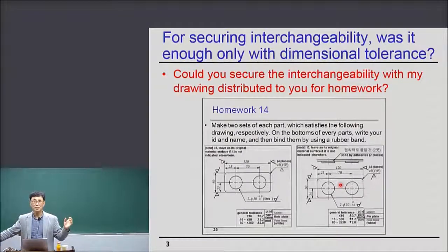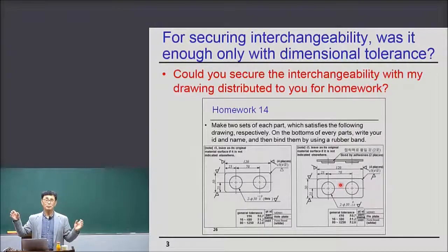And the MMC hole plate, what is it? Material maximum condition is when the hole is smallest, right? Then you try to insert the largest pin into the smallest hole. Then the center distance of the MMC pin plate and MMC hole plate is the problem.